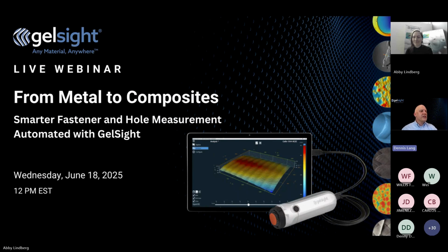Of course, getting your first pass assembly, being confident in what's going on, and real-time feedback. So you know if your drillings are right, if your finishing processes are getting where you need to be. Very important when you think of drilled holes and also rivet quality. We have scenarios where the first application of GelSight in a new company was actually looking at rivets that were being damaged going through the feeder, and they were finding damaged rivets in the holes, and they had to trace that problem back with GelSight to the rivets coming through the feeder being damaged, so they were able to trace down where that was.